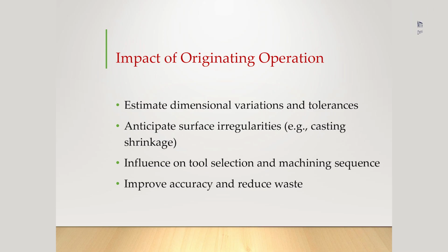Certain engineering drawings provide more explicit details by including multiple sets of drawings, such as a forging drawing and a machining drawing. The forging drawing shows the raw shape of the material before machining, while the machining drawing highlights the final dimensional specifications. By analyzing both, the engineers can predict how much material must be removed and which machining operations are required to achieve the final design.